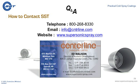Excellent. One of the best features of cold spray coatings is its ability to hold compressive forces. I mentioned earlier that we can design some well-adhered, highly densified coatings, sometimes with less than 0.1% porosity. That's a volume-on-volume basis when we assess that porosity. Compressive forces are held extremely well with cold spray coatings. We've got plenty of customers who are using cold spray coatings in weight-bearing or force-bearing situations, and the 356 alloy is a perfect example where cold spray application would be very well suited for that repair.